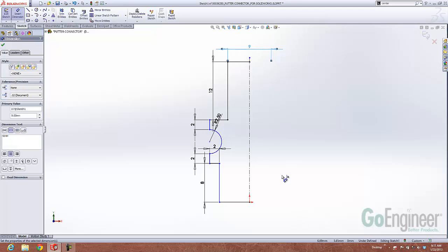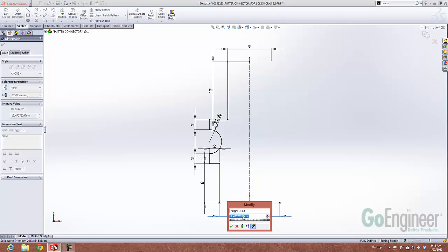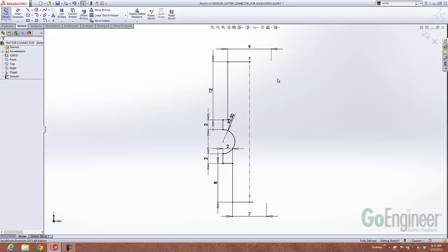And if you remember from, I think it was last year's release, SOLIDWORKS remembers the fact that I had the center line selected, so when I make another click, I don't have to reselect that center line. We can just say this is going to be 7, and I've got my geometry. So adding dimensions as we're sketching without having to worry about over-defining or over-dimensioning the sketch. Just by not placing a value into the dimension, it won't place the dimension.